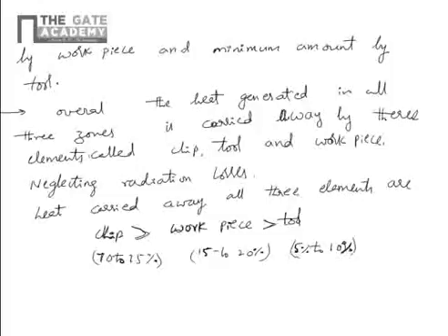And the workpiece is also the same. So if the workpiece is taking heat, the tool will also take it automatically. That's why the heat generated has to go out with the help of the chip, because the chip is moving out. Because the chip is carrying away the maximum amount of heat, the temperature rise of the chip is very high.